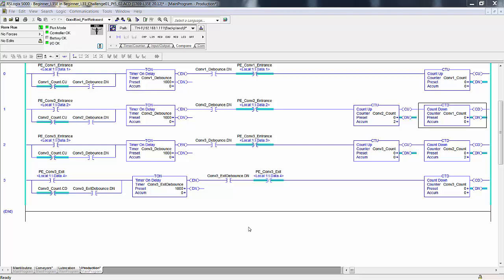For the logical conveyor control, we will get more methodical and write a quasi-functional specification for each of the outputs, 3 in all of which are conveyor motors. In the following logical statements, we leave out the condition of system enabled being true. It is assumed for all rungs.